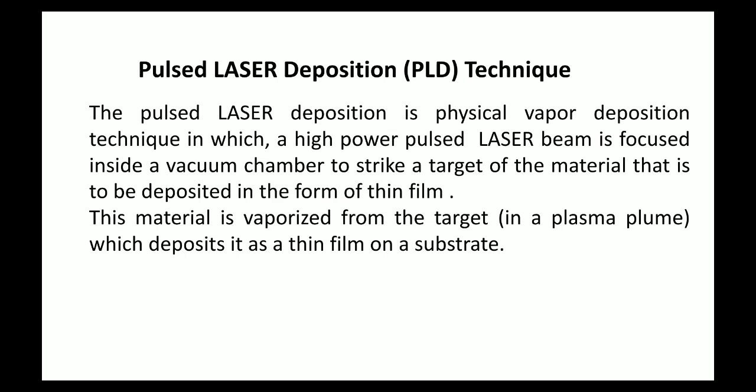So this laser pulse will generate a plume. What is a plume? I will show you. It is called a plasma plume. It is generated and the material starts to get deposited on the substrate. After a sufficient number of pulses, you will get sufficient thickness.